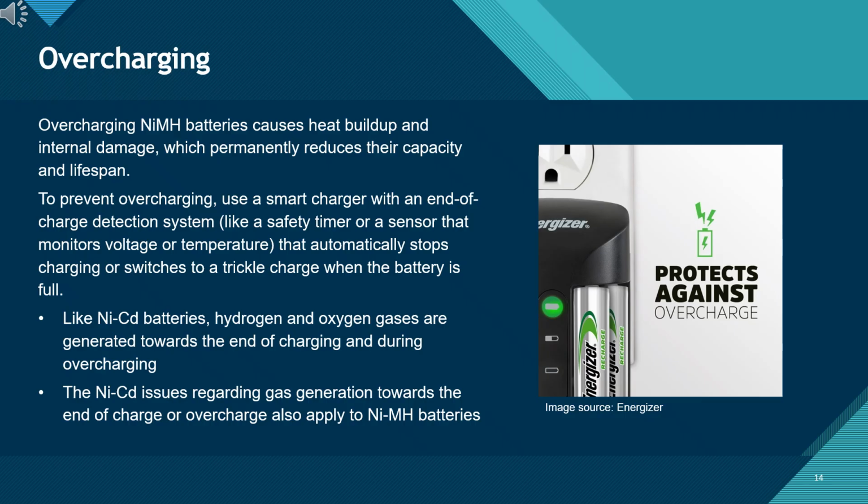To prevent this, smart chargers use safety timers and sensors that monitor voltage and temperature, automatically stopping or switching to trickle charge once full. That's why using the right charger is essential for safe and long-lasting operation.